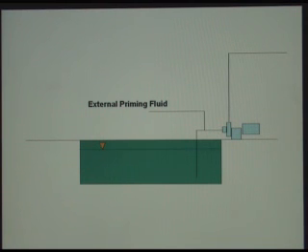If this is a 20-inch line, you're talking some huge flow rates to be able to fill that line up because there's no restriction at the bottom, and it's going to go to the path of least resistance. So conceivably, if your level is high, you can overfill your sump before you actually get the pump up and operational.